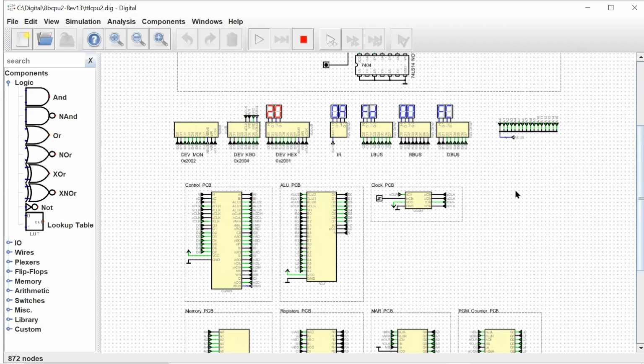It's a completely deterministic solution. It's based on our 4 clock phases, and there's nothing in there that's dependent on any built-in delay circuits for our timing. And I'm pretty confident. Again, we're going to start out my TTL computer 2 with a 4 megahertz clock, and I'm pretty confident that we can easily go up to a 6 megahertz clock, and we'll be running fine at 6 megahertz. So that's it for today.